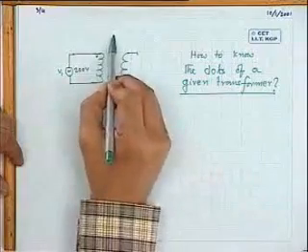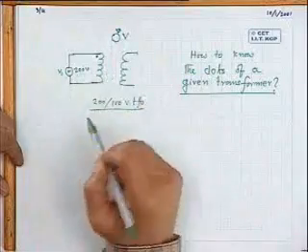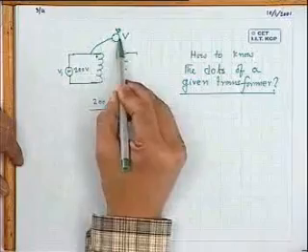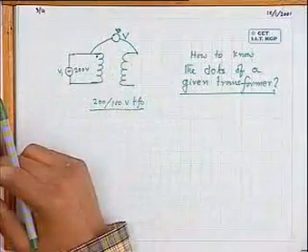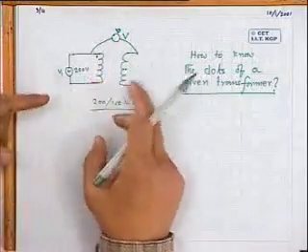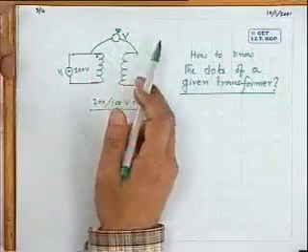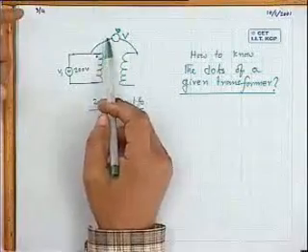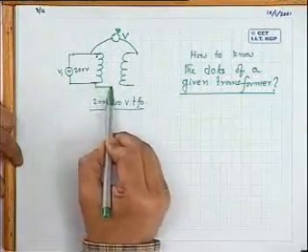So you apply a known voltage. Now you take another voltmeter. Take two wires. Connect one here and another there. How much will be the reading of the voltmeter? No, it will be 0, because where is the closed path? Right now, up to the point I have drawn, it will not read anything. Because potential is always between two points, you should start from one point and reach the other. Right now, it will not read anything.